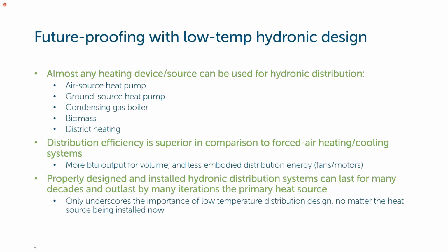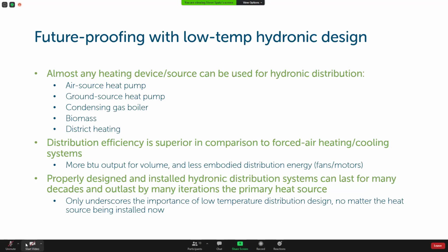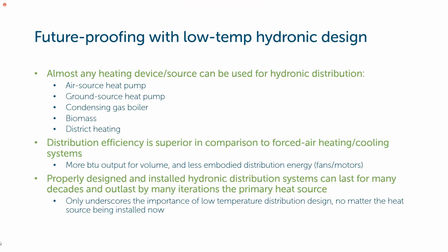So what we're getting at with any hydronic system now is aiming for low temperature distribution. Standard fin tube baseboard is about 180 degree water that you're moving through the building in different ways. You can have series loops, you can have parallel loops, but ultimately your output and the whole system basis is around creating hot water that's being distributed throughout the building.